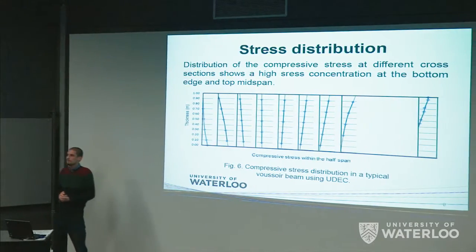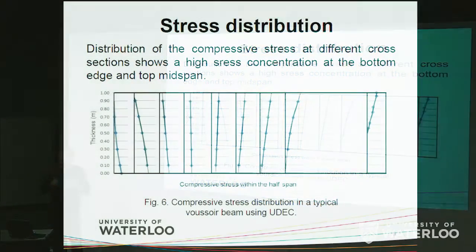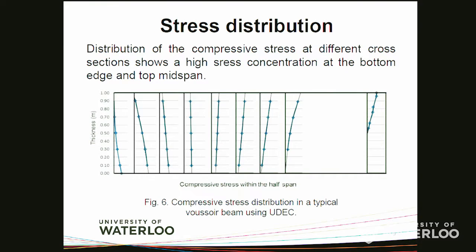Remember that I said the stress distribution within the beam looks like an arch, and that's because the method is called Voussoir beam. Just to clarify and verify this idea, I've used a software called UDEC. It's based on the distinct element method, and it's used to model discontinuum media. I've used UDEC to simulate the stress distribution within the beam.